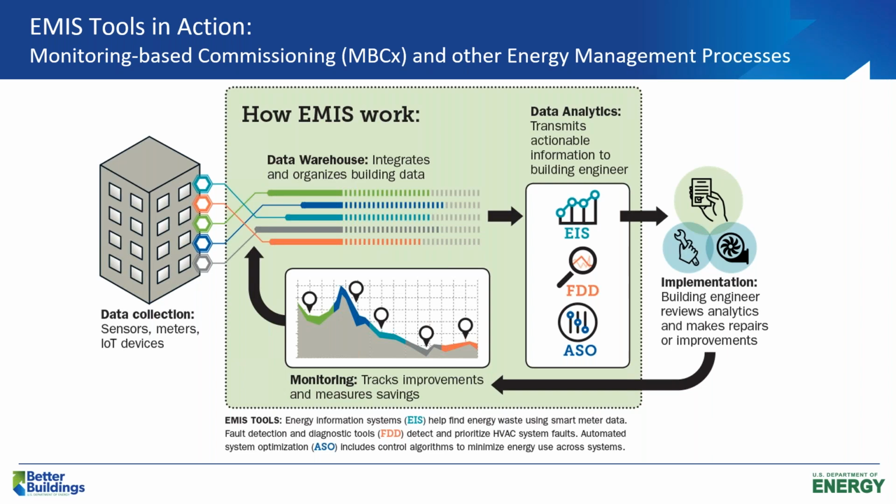And instead of just fixing something and hoping it was fixed, you can actually verify that it was fixed. So monitoring-based commissioning is a term that's used to look at a comprehensive energy management program that's continuously looking at the data using an EMIS. But really any energy management program can use an EMIS. It doesn't have to be as comprehensive as MBCx.